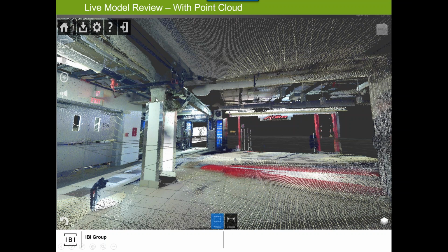And you can see here in this image, this is the review, and this is what a BIM coordinator would have identified to say, hey, structural and architectural, now if I remember, this is the point cloud, this is the column, or vice versa. There's an adjustment that has to be made because the model in Revit is not matching the actual physical as portrayed by the point cloud. So it's a very powerful tool when used correctly, with a good workflow, you've got good synergy.